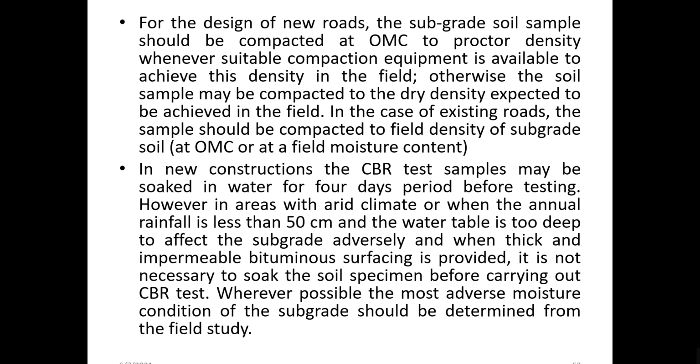In the new construction, the CBR test specimen may be soaked in water for 4 days before testing. However, in areas of arid climate, or when the annual rainfall is lesser than 50 centimeters and the water table is too deep to affect the subgrade adversely, and when a thick impermeable bituminous surface is provided, it is not necessary to soak the soil specimen before carrying out the CBR test. Wherever possible, the most adverse moisture condition of the subgrade should be determined from the field. So what does it mean?